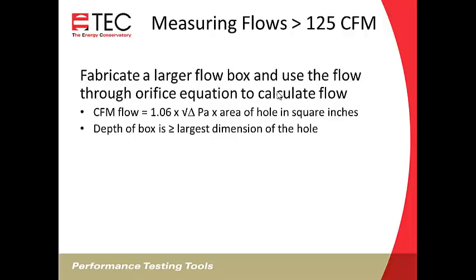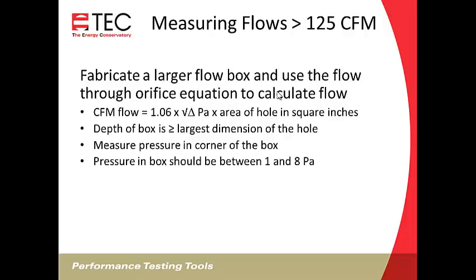The depth of that box you're using needs to be greater than the largest dimension of the hole. So remember that. You can't use a shallow box. The laminar flow is going to throw you off, and you're not going to get an accurate reading. So the box needs to be at least as deep as the largest dimension of the hole. Measure the pressure in the corner of the box.